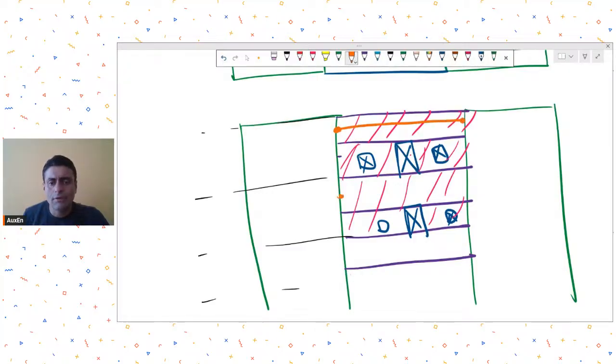Now, what I have observed in ETABS after comparing both these models is that if you do it as a spandrel shell element, of course, these shell elements give you better and more realistic results. But even with beam elements, that means modeling your deep beams or spandrels as line elements or beam elements, your results are not off the mark by a large degree.